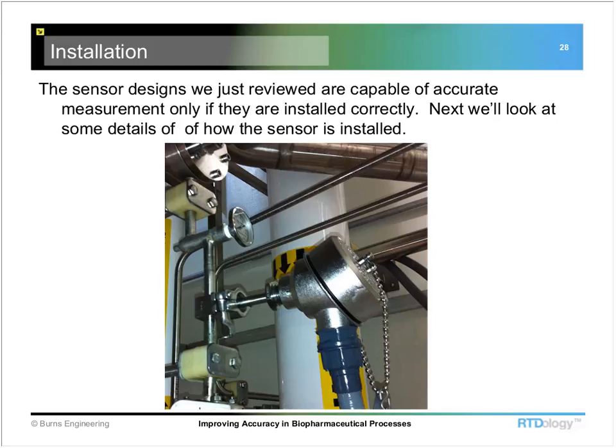Well, I guess if we look at what we've seen with like that 1/8-inch diameter mini sanitary, the first one we looked at, we get by with about 1.1 inches of immersion. And there it uses a sensing element that only has a sensitive length of probably just over 1/8 of an inch, and the tubing is 0.125.